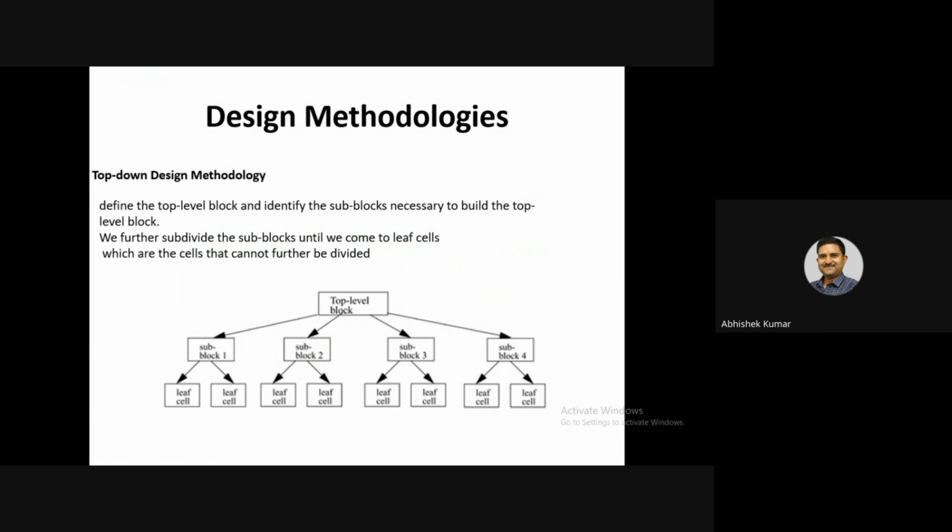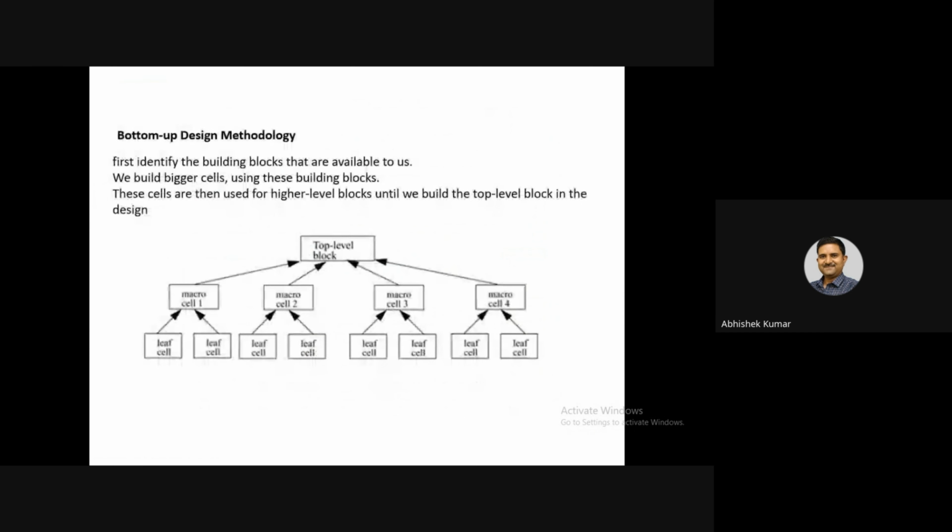So either we can think about this type of designing. One is called top level designing, wherever one complex circuit is divided into different smaller blocks, and every smaller block is designed with logic gates. So we are moving from top to bottom. Or we can have the opposite case, the bottom to top methodology. First of all, with the help of logic gates, we make the micro cell or a smaller block, and again join the smaller blocks to make the top block.